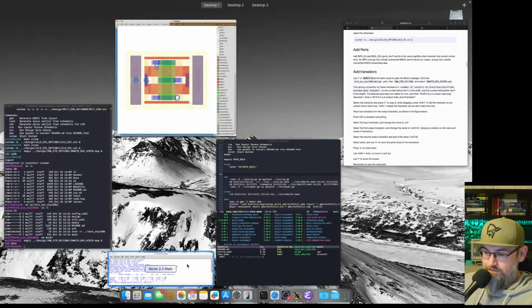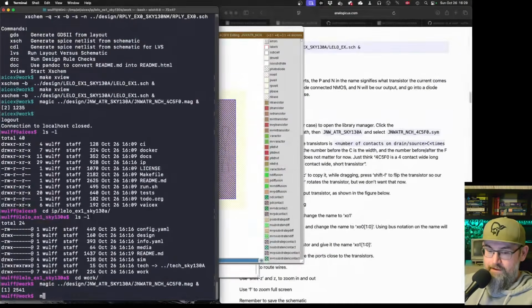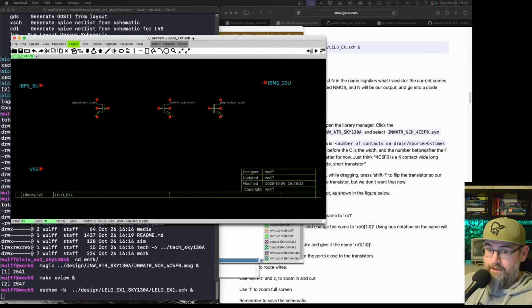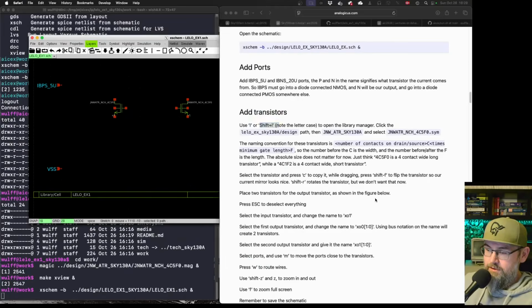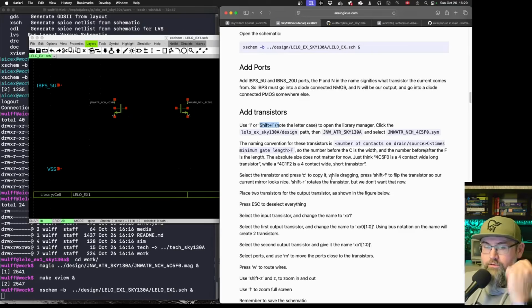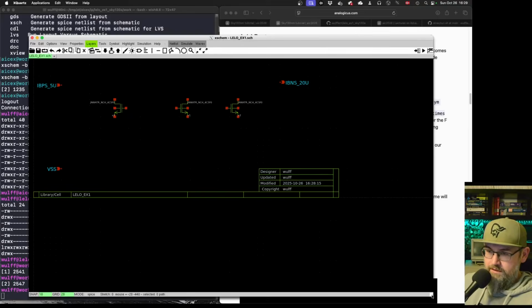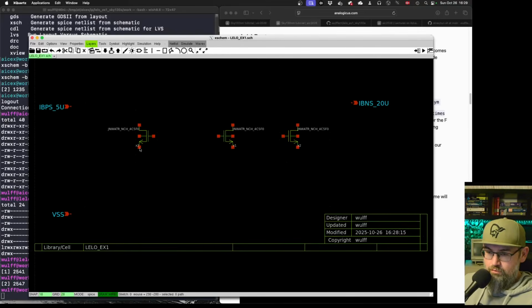And let's do the same for, yeah, I closed Xschem. Let's open Xschem also. Okay. So let's continue the tutorial. So what we want to do is draw this current mirror. So in Xschem, you have to press the W command in order to wire. So let me do that again. You press the W. I can go down here and over here. Every time I'm changing corners now, I am pressing W.